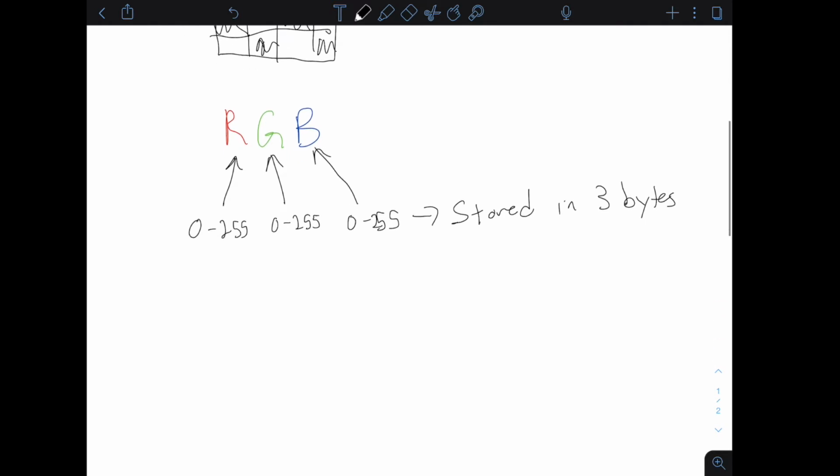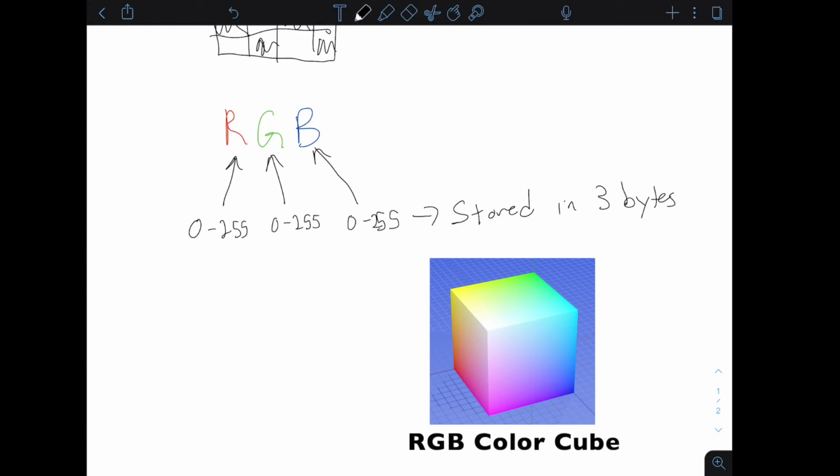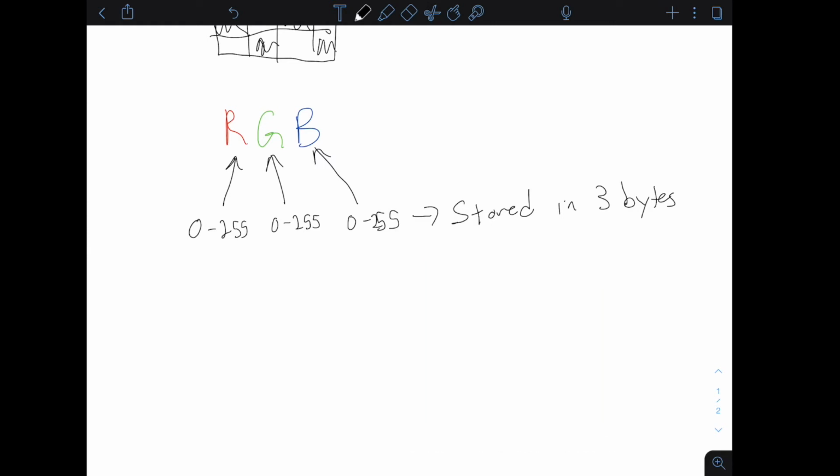Whereas when we're operating robots, if we go into a dark room, we don't want the robot to stop working. We want the robot to still be able to detect that red object or that blue object. So it turns out that there's a better type of color space, as it's called. Instead of just using RGB, which is what we're most used to, often in robotics, we use HSV color space.